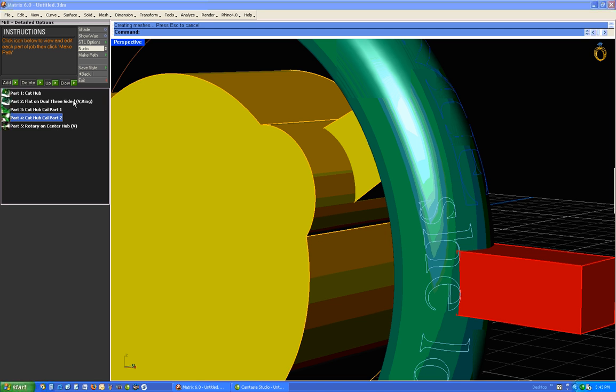Now, be careful whenever setting up the follow curve's cutting angle for side or flat cuts. It is always possible to have the cutter enter the model from the wrong side, destroying the model. I'm going to do that now.